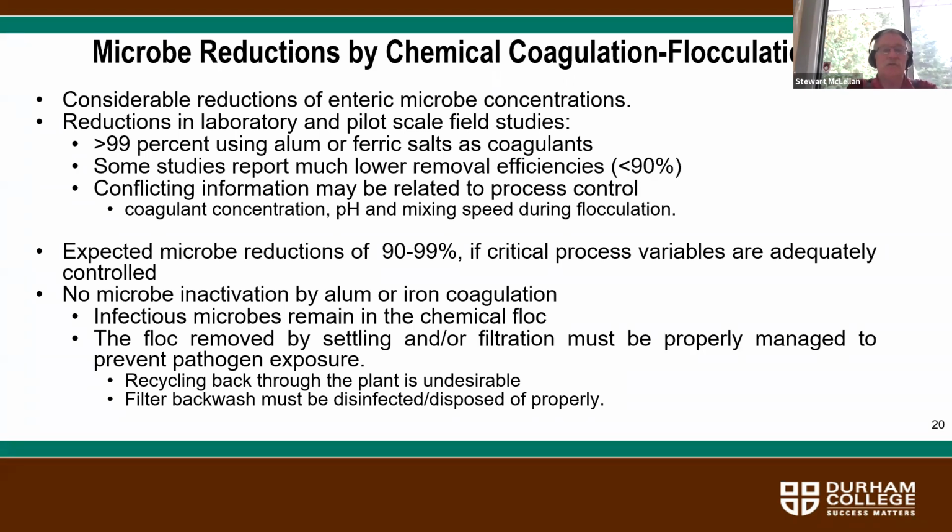Expected microbe reductions are 90 to 99% if critical process variables are adequately controlled. There is no microbe inactivation by alum or iron coagulation. Infectious microbes remain in the chemical floc. The floc is removed by settling and/or filtration, and must be properly managed to prevent pathogen exposure.